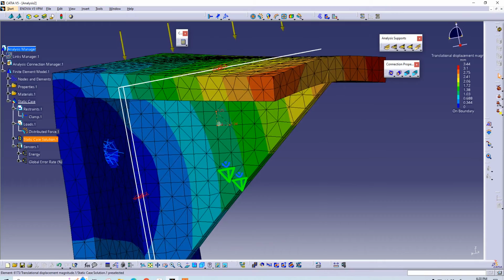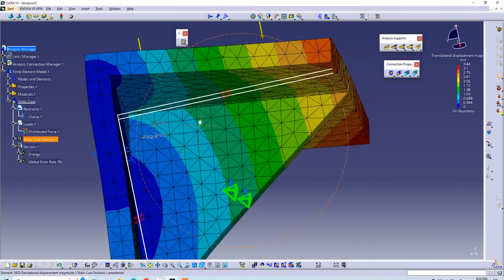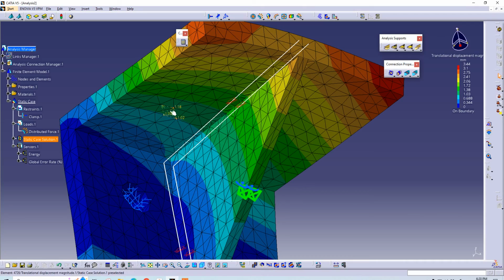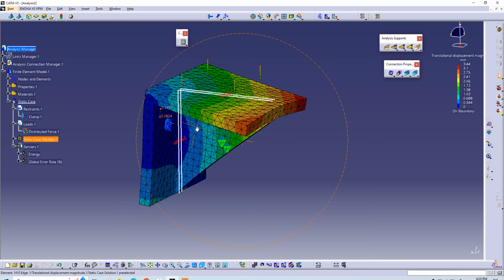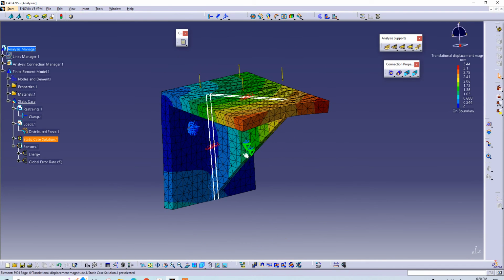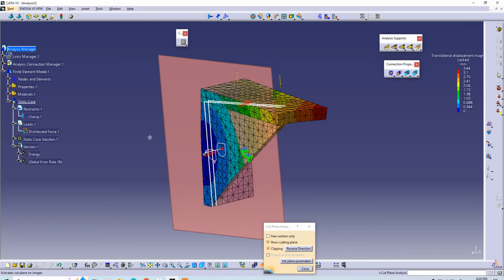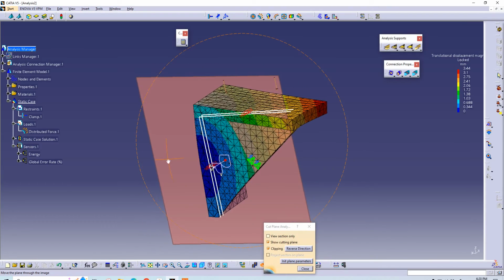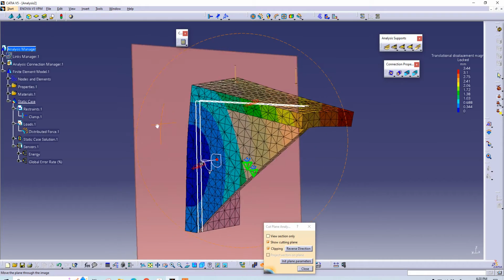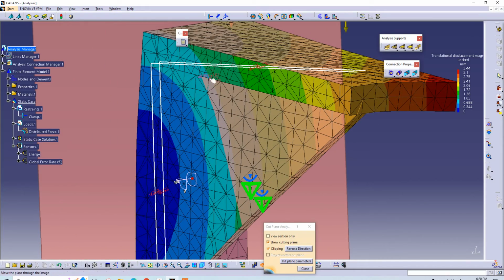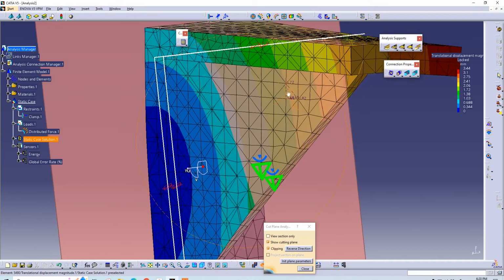By using the line connection and welding properties, you see that it's as if these 2 elements are a solid. That's the way we want to simulate properly for an assembly. In this example, I use line properties, line connection, and seam welding on the line. If I cut these 2 into their cross section, you can see that the nodes and elements are connected properly.